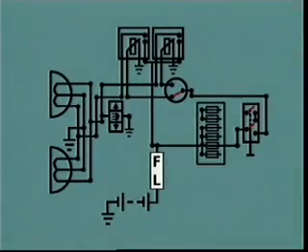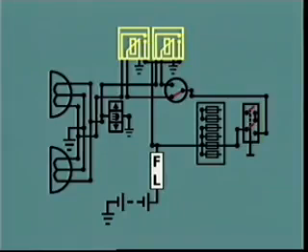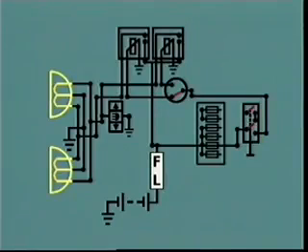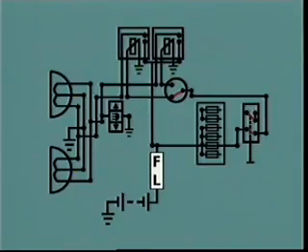The headlight circuit consists of the battery, fusible link and fuses, headlight switch, headlight relays, dipper switch, headlights, high beam indicator light, wiring of a suitable size to carry the electric current through the circuit, and the ground circuit. When the headlights are switched on, current is applied from the battery through the fusible link and fuse across the closed switch contacts to the dipper switch.